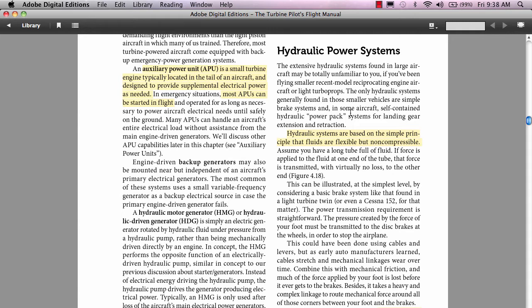Now, I guess if you were operating an electronic fly-by-wire aircraft, you wouldn't necessarily have to have a whole bunch of backup. But even on these aircraft, like the Airbuses that use fly-by-wire technology, even their large gear extension and retraction and flap is done by hydraulic systems. So they can say they're fly-by-wire, but they still have hydraulic systems on board their aircraft to do the heavy lifting.